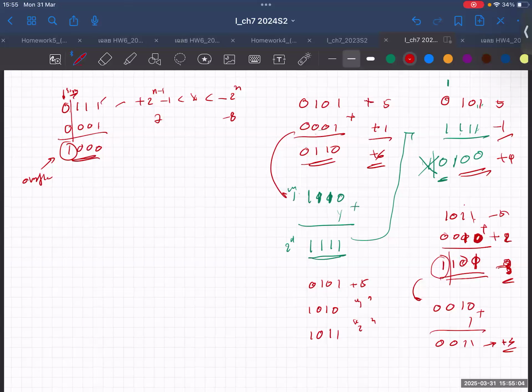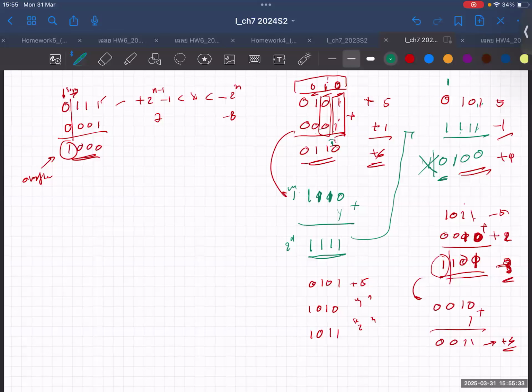But the trick is, when you add them together, as one bit here, what we do is one full bit addition, right? Remember that you actually add it with carry, right? So the first line is carry. For example, 1 1 0, you get 0 1, right? And 1 is the carry from the previous one. You got 1 0, right? Okay, this one is going to the other one and add them together. Remember that? And you get a 1 again, 1 0. So these zeros go up here, right? And add with the next one.